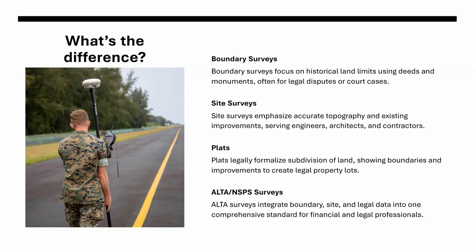So you can see the trajectory clearly. Our boundary surveys look backwards. Our site surveys look at the present. Our plats formalize ownership and use in legal records. ALTA surveys unify all of these into one standard product. Each step builds upon the one before it, and as a drafter, your responsibility is to be competent in each step, to know the differences, and to preserve accuracy and trust at every stage.